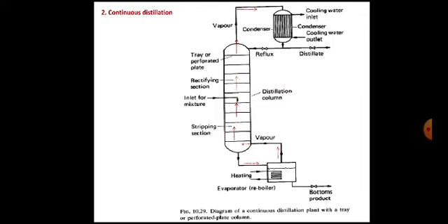Finally, the vapors will reach the condensation chamber, that is the condenser, where the vapors are converted into liquid form. Initially, the whole liquid or condensate is refluxed back into the distillation column. This is again required to initiate or to get the desirable temperature in the distillation column. This is done in the beginning only. Once the temperature is set, the reflux is not needed.